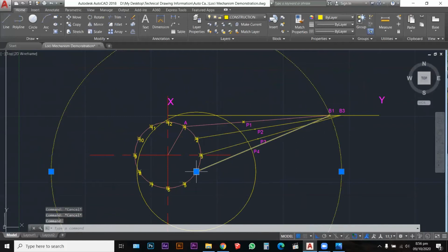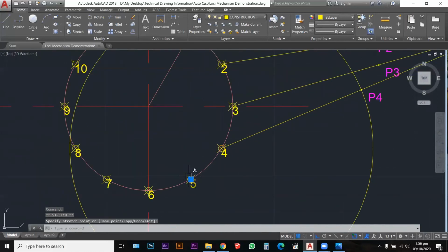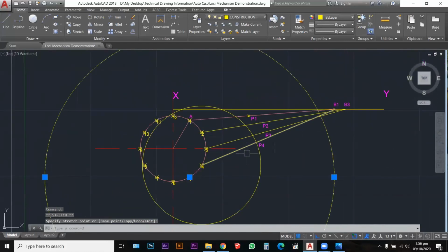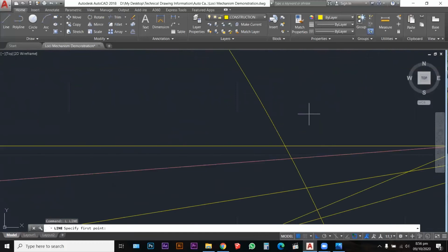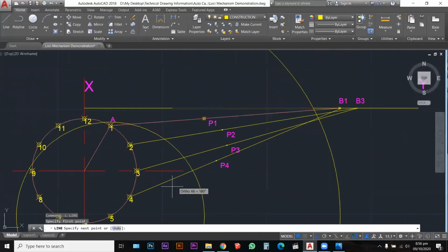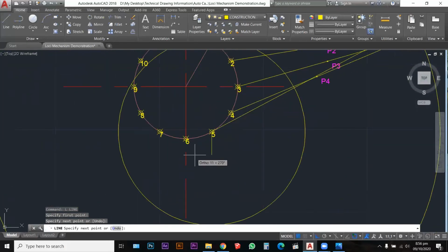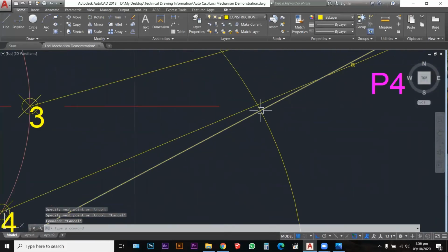I want to move this big circle, which is 110, the distance of the rod, to 5. You can see where it cuts the line, and move the smaller circle from 4 also to 5. So I'm moving 2 circles at a time. And it cuts the line right here, and then I make the connection to 5. I'm looking for where it cuts right here.